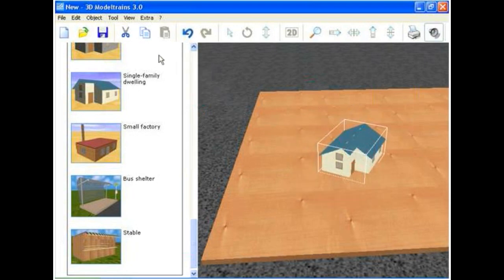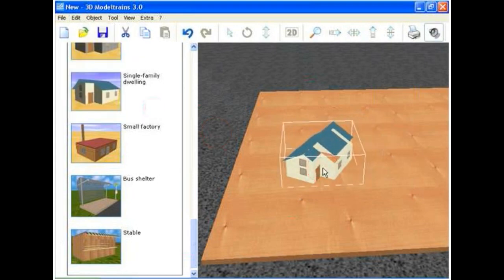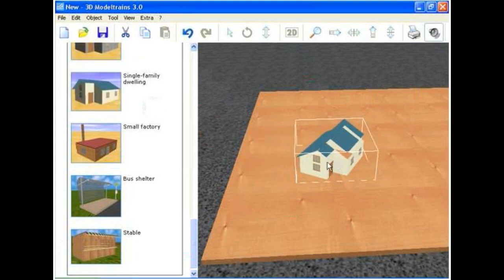Each object consists of a number of separate objects that have been grouped together as a single shape. To modify the object, you must first select Edit and choose Ungroup. You'll now see all of the parts of the object and can modify these. You can also regroup the parts into a single object again. First, select all the parts by clicking on them with the Control button pressed down. After selecting everything, go to the Edit menu and select Group. You now have a new object containing all selected parts.